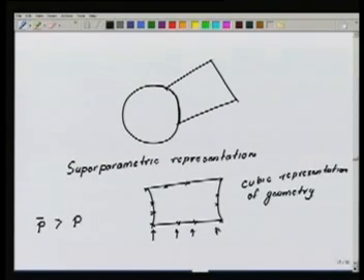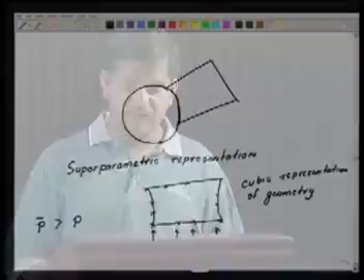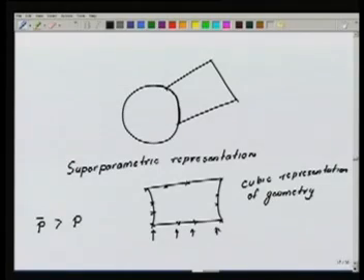This is not used normally in finite element applications because the necessity does not arise, but it may be needed in some application, and if so desired it has to be used. The bottom line should be that the error induced due to the inaccuracy of the representation of the curved geometry should not be significant as compared to the error that I am incurring due to the approximation of the exact solution. So this should be the bottom line with which we choose the representation.